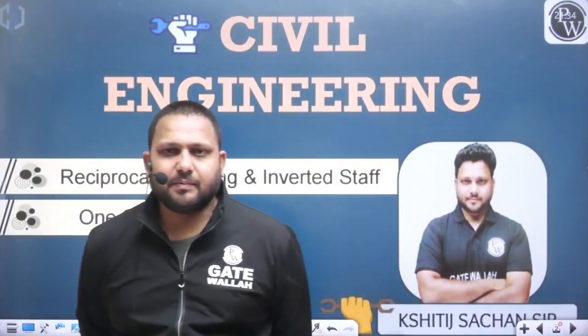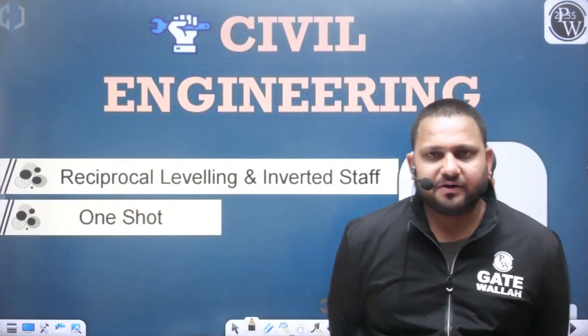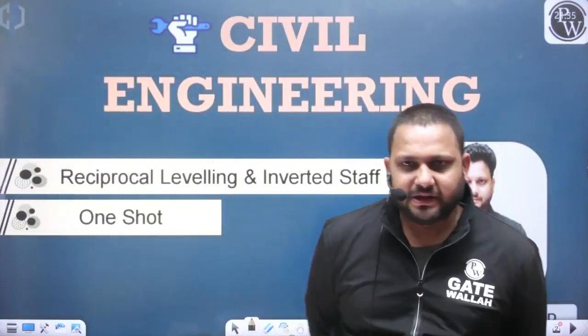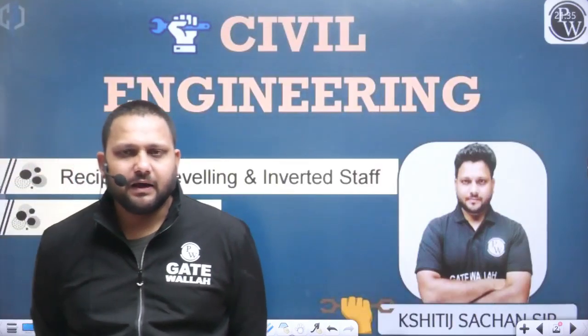Finally the combined correction that we got was CC equal to minus 0.0673 d square. When talking about the combined correction, in the measurement we considered the effect of the curvature as well as the effect of the refraction. Due to the curvature there was a positive error, so we applied a negative correction, and due to the refraction there is a negative error, so we apply a positive correction. Ultimately the overall correction will be negative. I hope that point is clear to everyone.